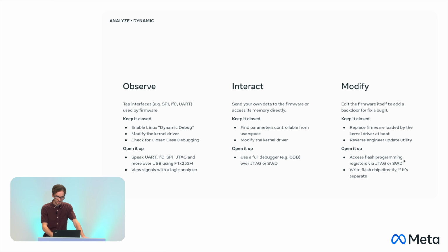But again, you can sometimes bypass this if you're willing to physically open up your device just for testing. Obviously, if you report a bug to us for bug bounty that requires you to open up a device and attach JTAG to some chip in order to run code, that's not going to be a valid bug because you're already at the level where you can do anything you want if you have the device open with test probes on it. But for research, it can be useful, and JTAG and SWD often let you bypass signing because you can just read and write the memory directly. You don't need to care about what's loading code into that memory.